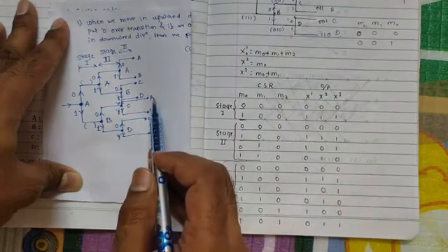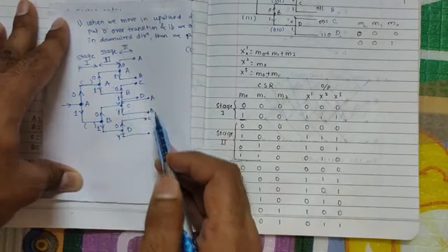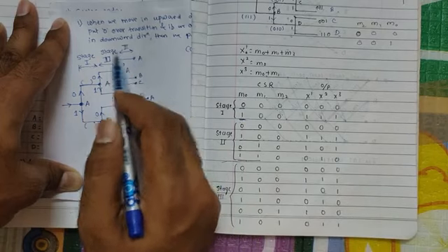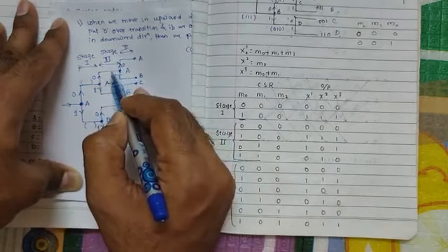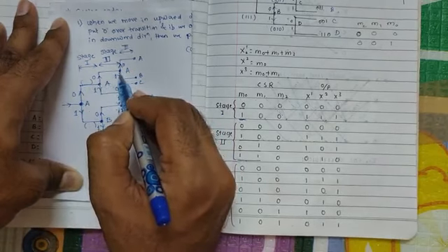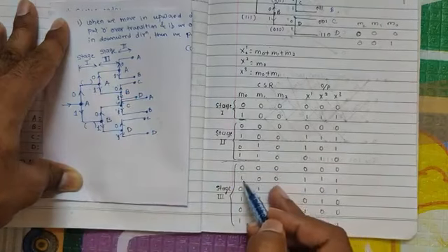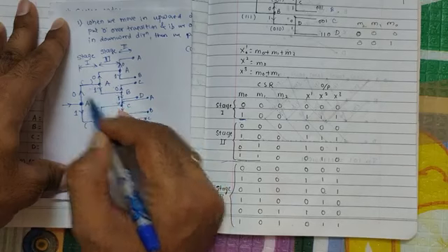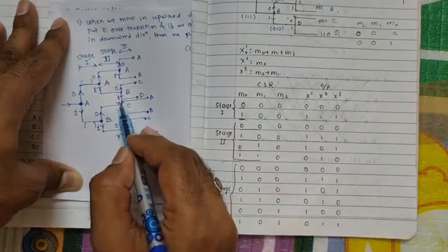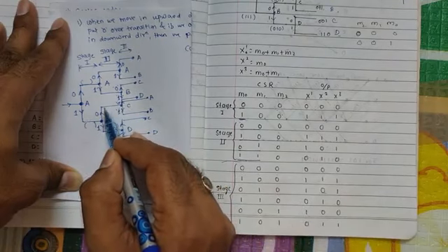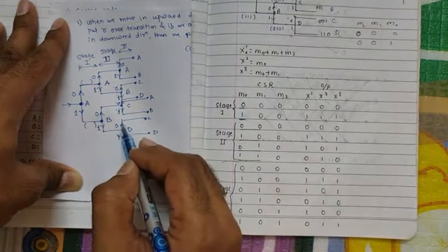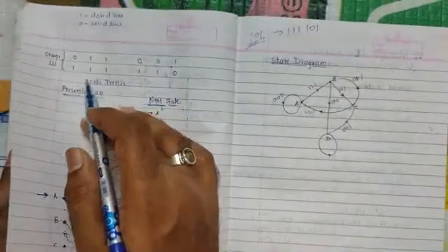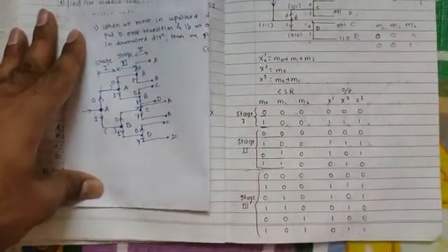Now if we are looking at the third stage, in the third stage the total number of output nodes are 8, and let us track now the inputs. So how can we track the inputs from final stage to the initial stage? So this is 0, then we are here, then this is 0 and then 0. So all 0, then 1 0 0. So I have written all 0, 1 0 0, then we are here. So 0 1 0, then 1 1 0. So 0 1 0, 1 1 0. Then next here 0 0 1 and then 1 0 1. So 0 0 1, 1 0 1. Next will be 0 1 1 and 1 1 1. 0 1 1, 1 1 1. So that I have written here 0 1 1, 1 1 1. So for this I have written their corresponding outputs also.